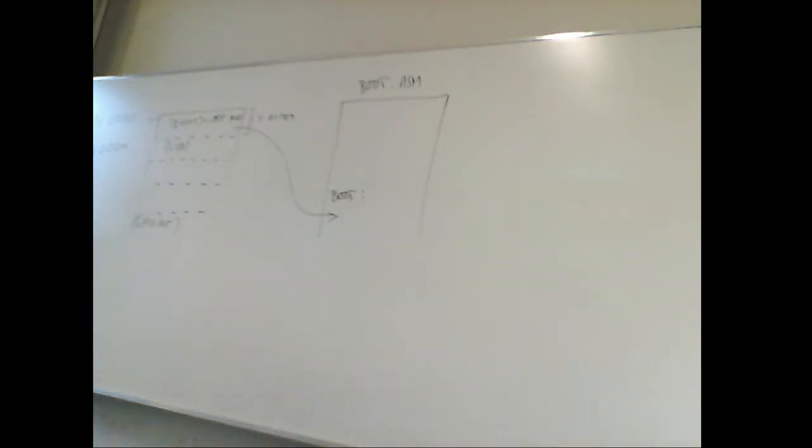So the GPIO interrupt fundamentally, and practically only one interrupt for all of the pins, which means that when we have an interrupting pin, any of those will cause the GPIO interrupt, which means basically here we have a long jump